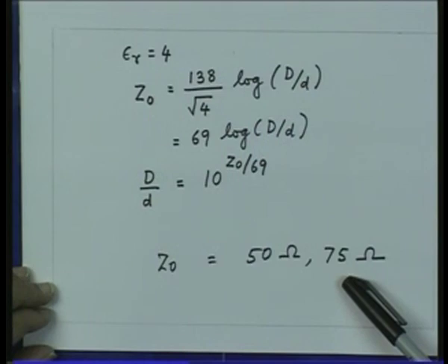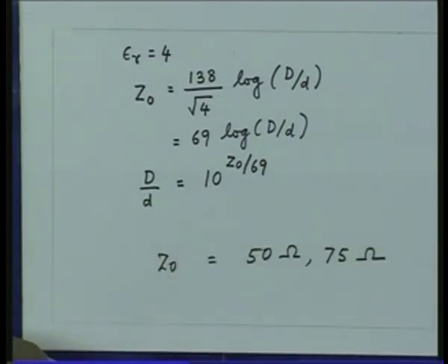So, just from the compatibility point of view of the impedances, whenever we use the cable for the antennas, we use the cable which has a characteristic impedance of 75 ohms. However, for most other applications or high frequency equipment, the impedance has been almost standardized to 50 ohms.